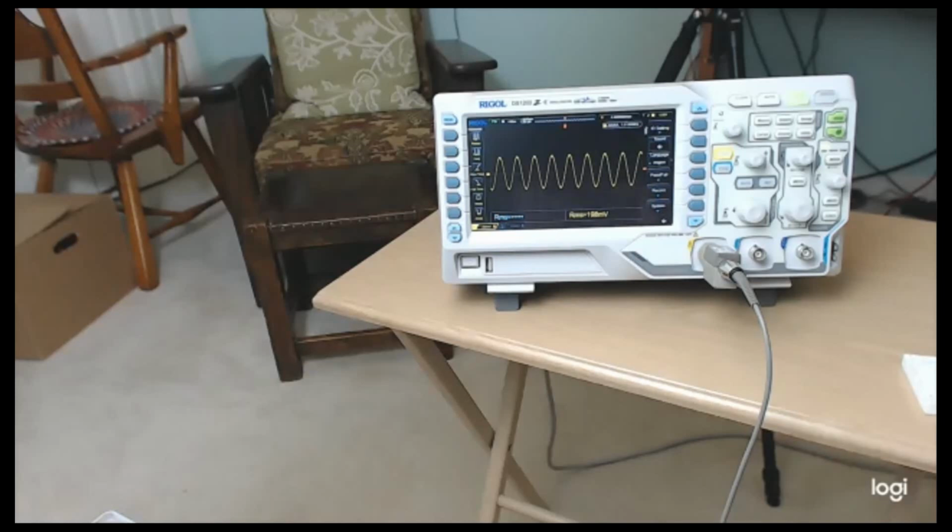So for instance, to write the code to control the AD9850 is complicated. There's a lot of complex signaling that has to go on to actually get that chip to generate the frequency the way you want it to, in the phase that you want it to. You don't have to think about any of that. All you do is say, okay, library, I want 7.2 megahertz, and it does the rest. You don't have to worry about the signal lines and all that. There are all those lines I hooked up; some software in a library that somebody else wrote is providing the actual controls for those. I just need to know how to interface to their library, which interfaces to the actual device.